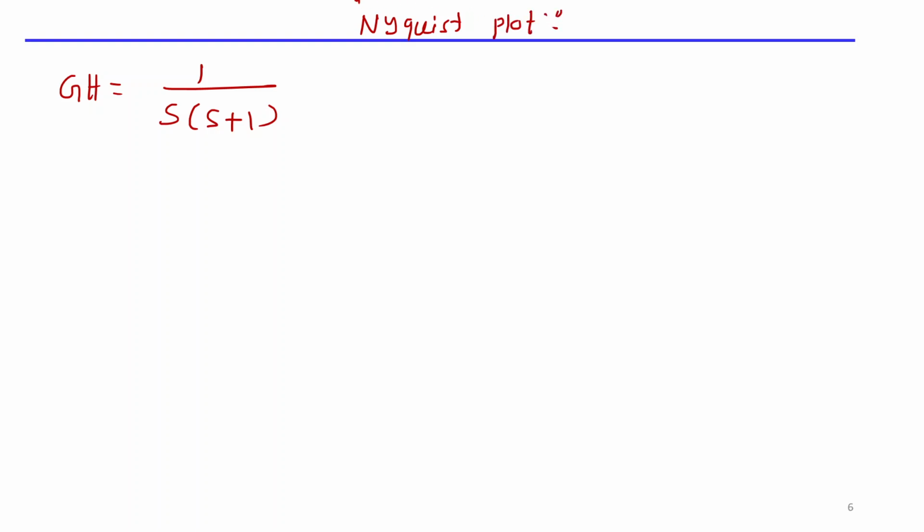I'm just showing you how to draw the plots, polar plot and Nyquist plot. So remember three things I will tell you in this slide. The first thing is that if a question comes to find the Nyquist plot, the first point that should come to your mind is to find the polar plot, because you are very confident about how to draw the polar plot.